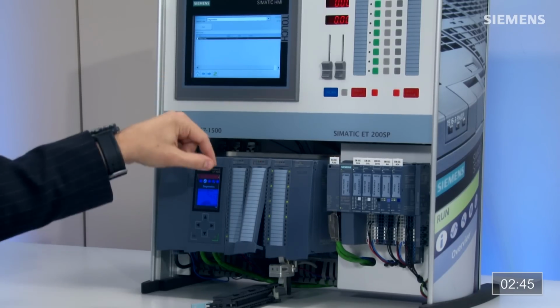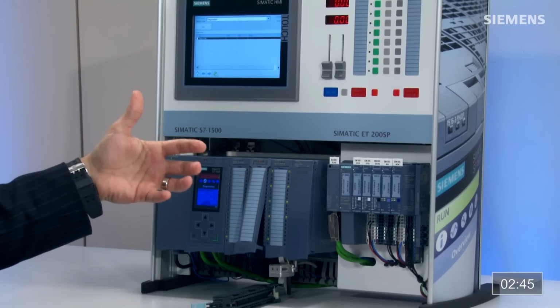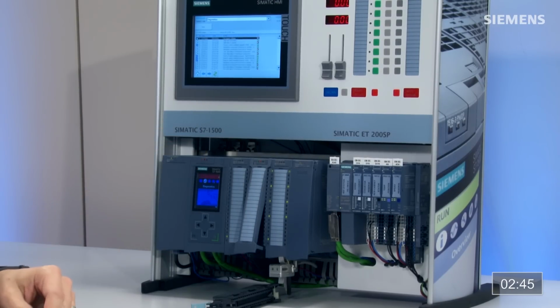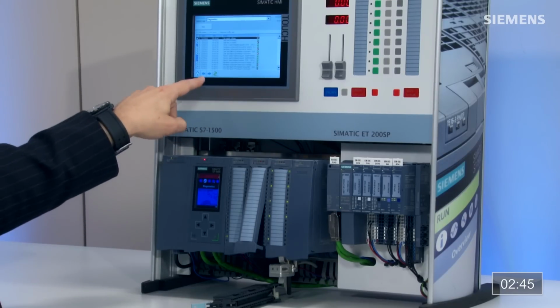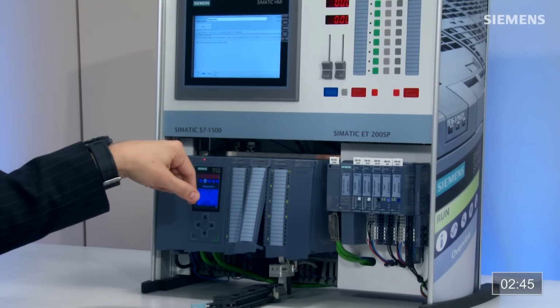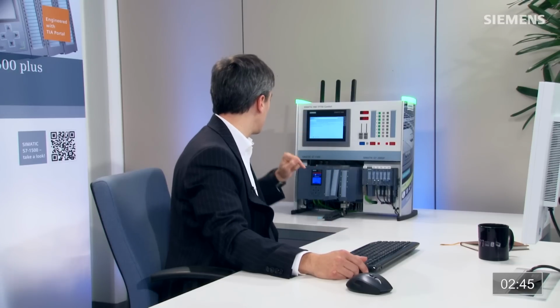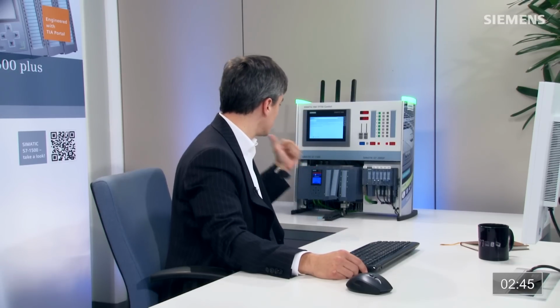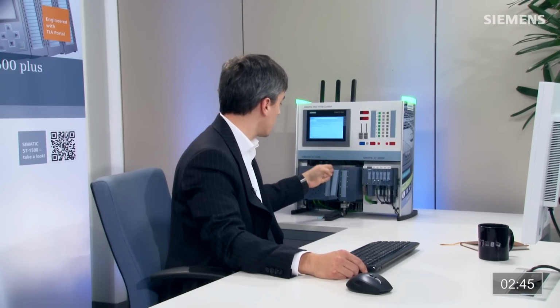I can click on this button right here. It's actually going to generate the ring buffer for it and show all the diagnostic messages. No supply voltage, that is correct. Click on the plus sign over here to find physically what it is. It tells us exactly that there is no supply voltage all the way down to the actual card in the rack and potentially how to solve the problem, including the part number, and not one line of code was required to achieve this. Now that is engineering efficiency.